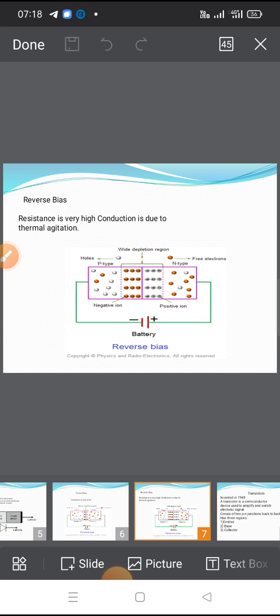In this process, the number of free electrons and holes goes on increasing. This cumulative effect is known as avalanche multiplication. Due to this large reverse current flowing through the junction, the diode is said to be in the avalanche breakdown region. The current is not controlled by external resistance. The diode may be permanently damaged.